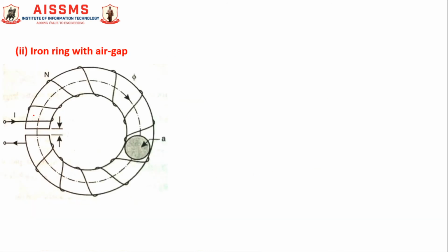Now in the second part, the iron ring with air gap. Make a cut of 1 mm in this iron ring. Therefore Lg is equal to 1 mm. Now with this, the iron length changes, and therefore calculate the length of the iron part, Li.